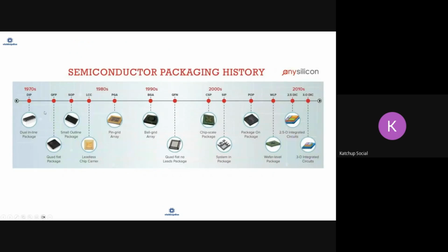So basically, we started in the 1970s. There used to be these kind of ICs which you would have seen in your electronics labs with pin and hole-based connection. Then as the performance requirement and pin connections requirement increased, multiple other technologies came in. We reached ball grid array here. Then SoCs, system in package, package on package, and it evolved towards 2.5D integrated circuit and 3D integrated